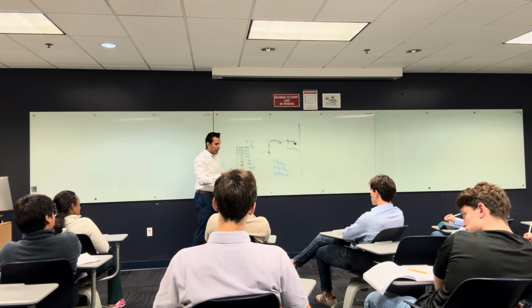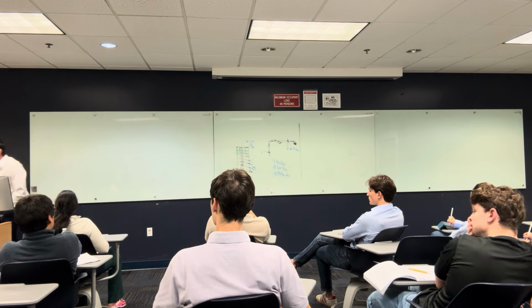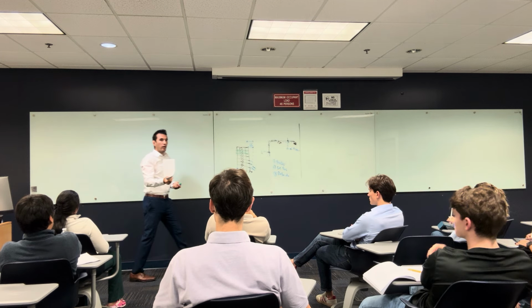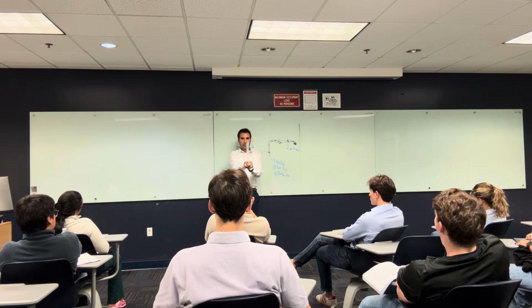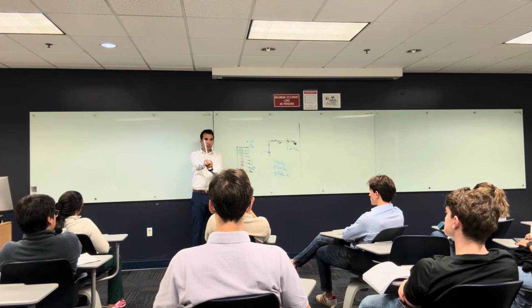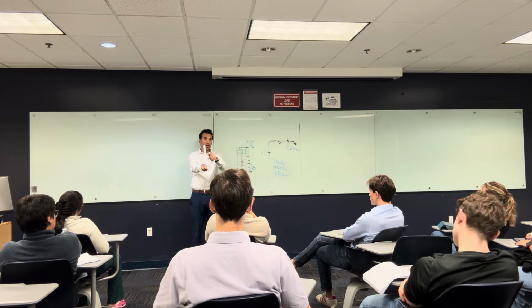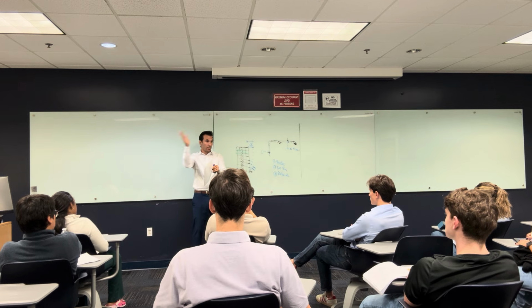The problem is when you have an earthquake or something, this mass is the one that causes all the deformation. Let's say this is my building, all right? Your building is like this and the ground is shaking. The slab is really heavy and at a really high elevation. So what is going to happen when the ground shakes is that the slab keeps getting thrown by the earthquake, right?